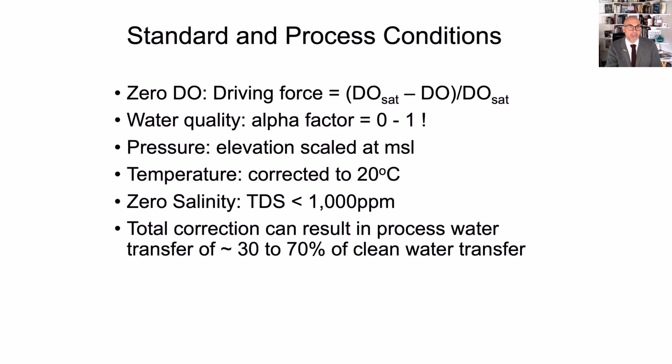Now, 0 DO means that the driving force is 0, because depending on the driving force, different processes will have different performance. It's very difficult to put the last molecule of oxygen, whereas it's easiest to put the first molecule of oxygen when there is none in the water. So to make sure we compare everything on a level field, 0 is 0 for everybody, since saturation depends on the location of the test.